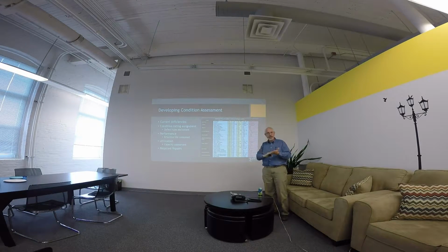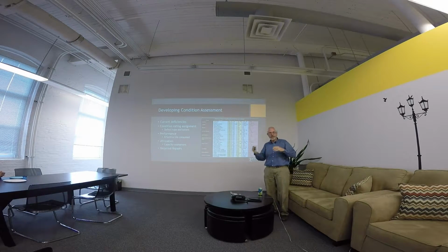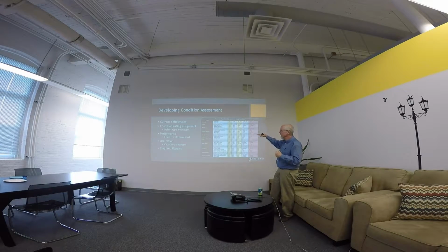For pumps, it might be vibrations, so you can measure vibrations. A lot of times, some equipment vibrates more than others, so you can't just say if it's vibrating at this level, it's failed. What you have to do is see what the vibrations are over time and see if it's getting worse. Usually it doesn't get better. I always tell people don't expect it to improve, so you're looking at deterioration in standard. So you look at the defect type and then look at the extent.